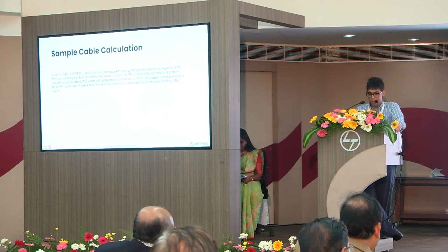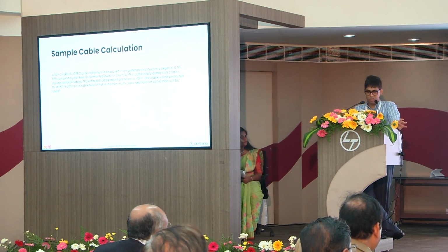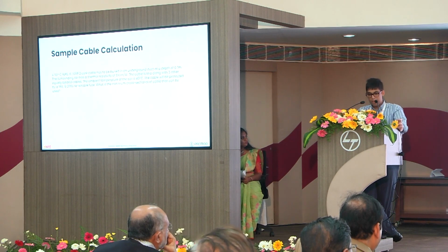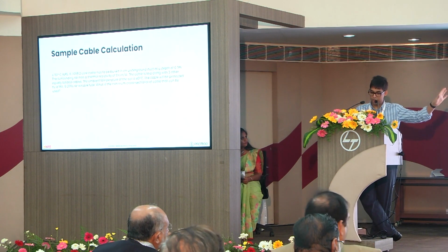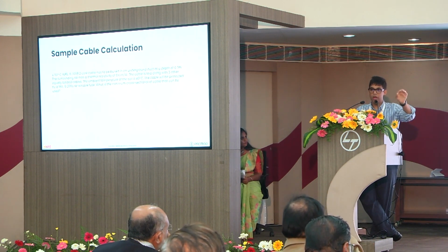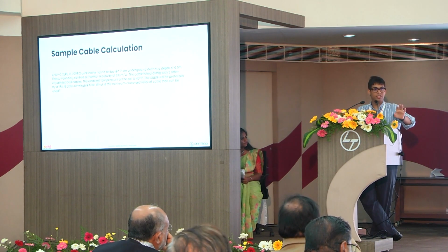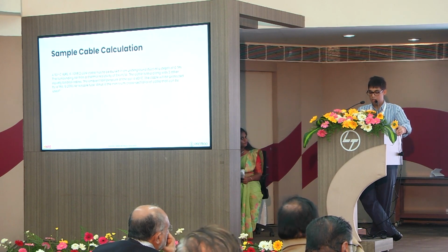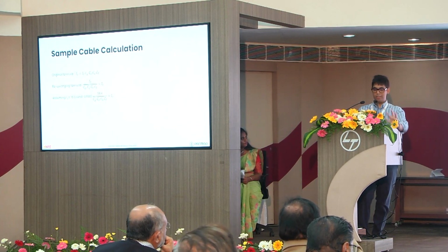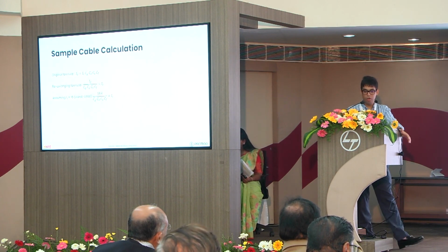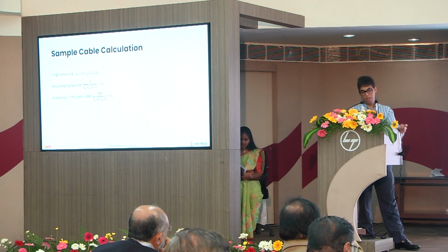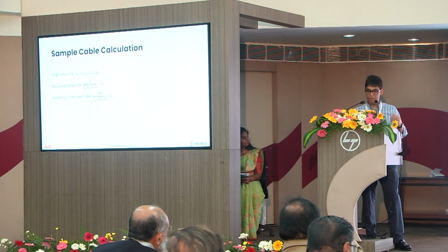Okay, now I really encourage you to follow along. This is a sample question. All you need to do is, I'll give you the formula, I'll show you the tables enlarged, just select a value and multiply them as per the formula. Is everybody clear on this? Okay. So let's rearrange the formula a little bit and make a couple of assumptions. This is our original formula. Let's assume that in the worst case scenario, Iz is equal to 16 amps, which is the rating of the cable.